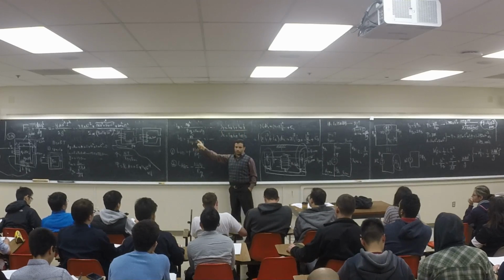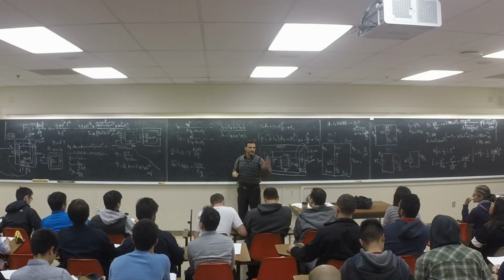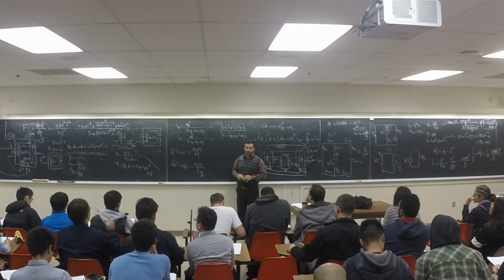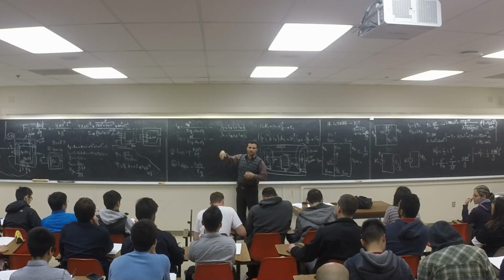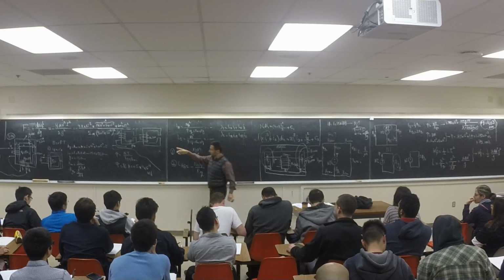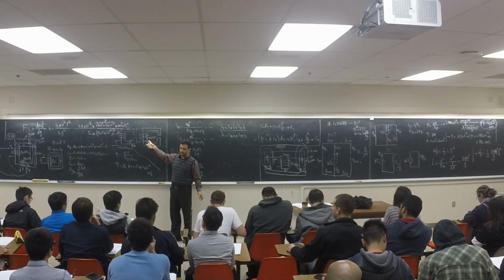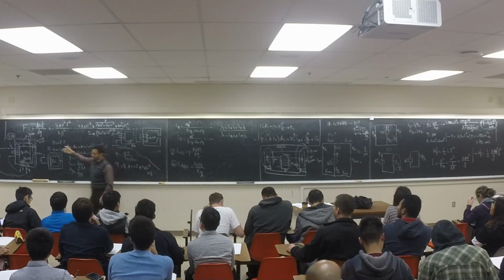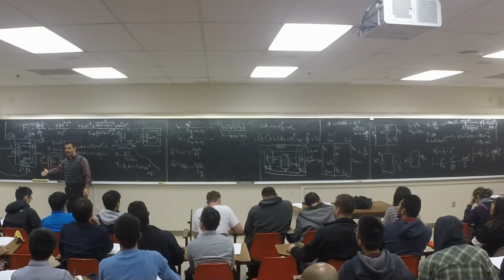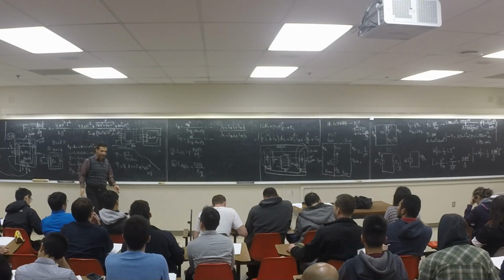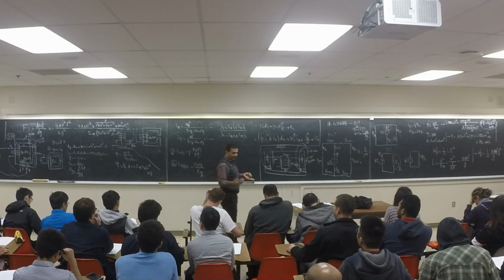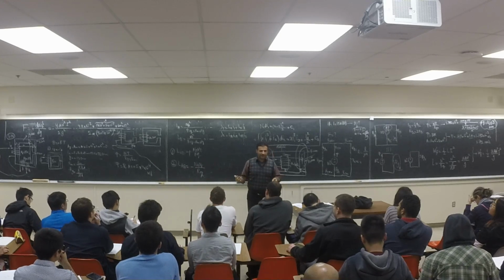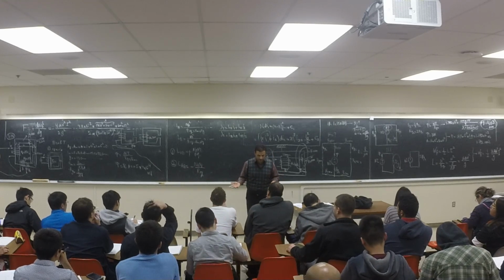Case 2, look at case 2. If I didn't have winding B, my flux is going to be more, right? Because for case 2 now it looks like 200. A by itself is 350, right? If I didn't have the B, I'm going to have more flux, because my current is 350. Basically, winding B is reducing the overall flux, right?